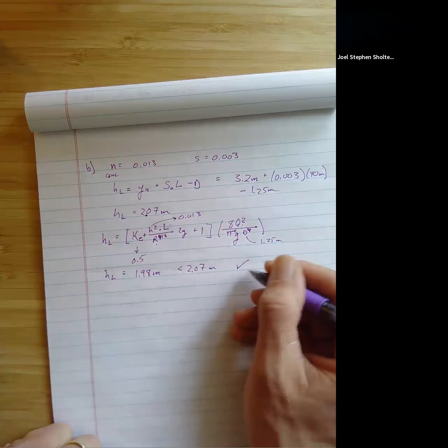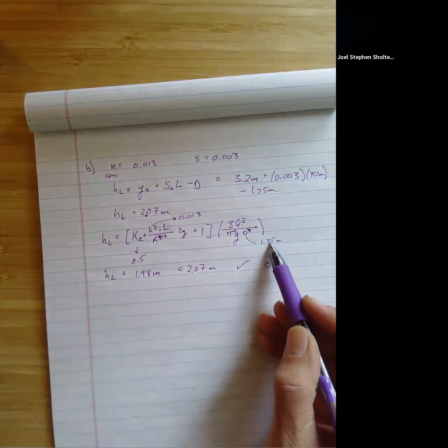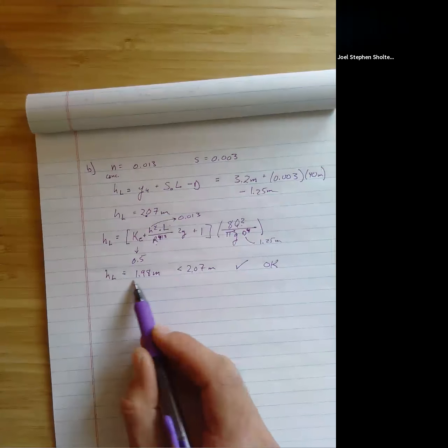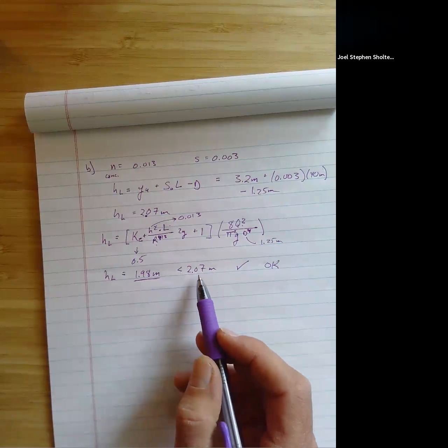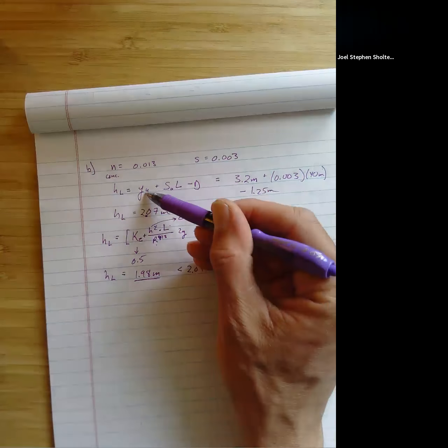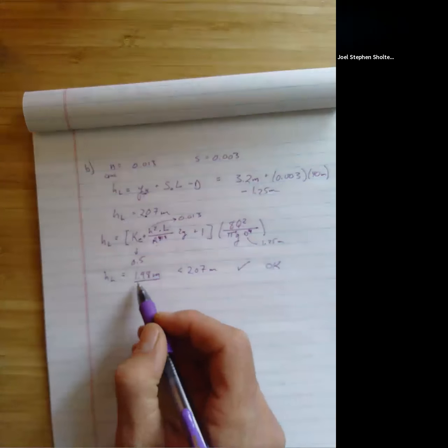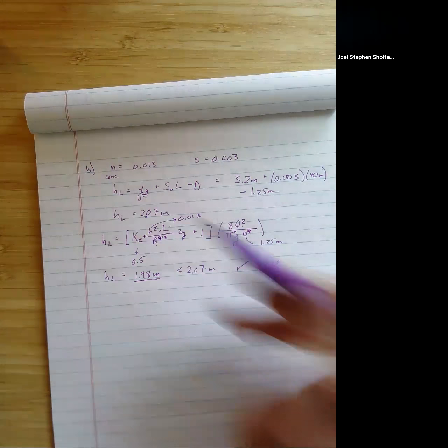So we're okay. And what that means is the actual head loss in this system with this diameter pipe and this roughness, this length, results in this head loss. And because it's less than the maximum head loss we can tolerate with this given backwater upstream, we can use this diameter with that smoother pipe and this backwater.